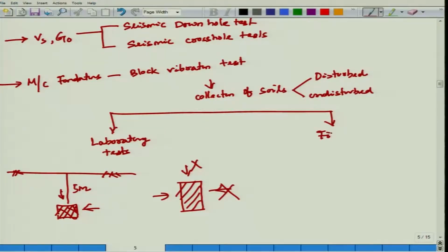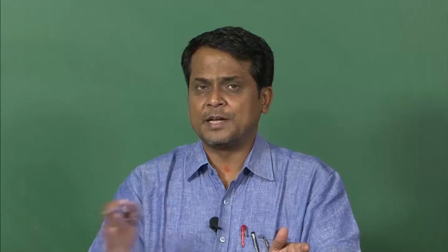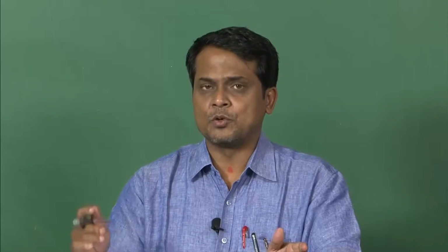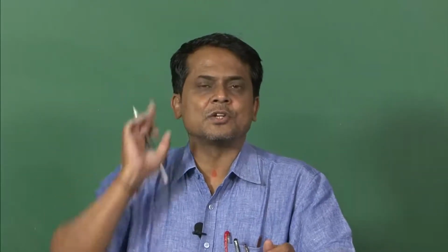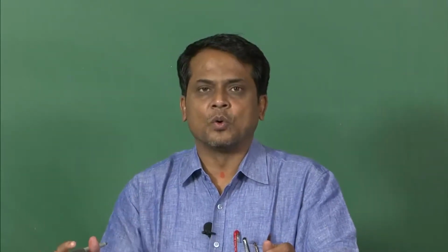So, then your field test. First one is boring, boreholes, collection of soil samples, disturbed, undisturbed. Then there are two parts. As I said earlier, the cost of the testing or soil explorations will be 0.1 to 0.5% of the total cost of your entire building or entire structure. So, you cannot spend more. Here laboratory test, second part is field test. Whenever it is required, you go for a field test.